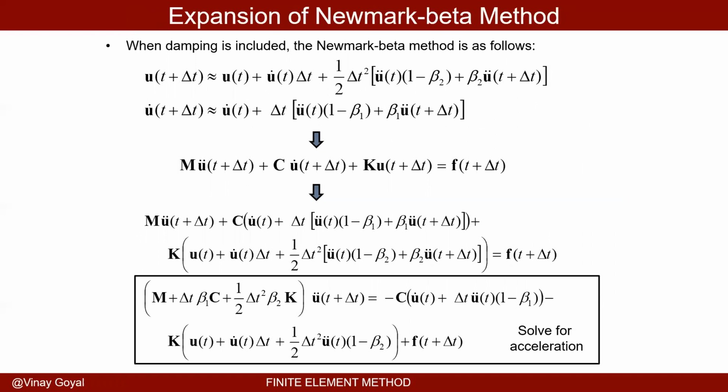So just to remind you one more time, we can use the Newmark beta method, but we can expand this for damping, because previously I did not discuss how to deal with damping, but it's the same thing. You have this equation here, this approximation for U bold, which depends on the velocity and depends on acceleration. And the beta here is a value that you prescribe based upon which time integration procedure we want to use.